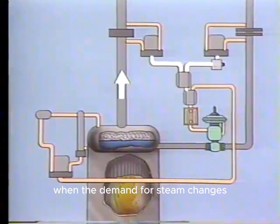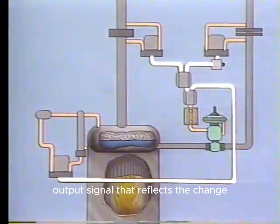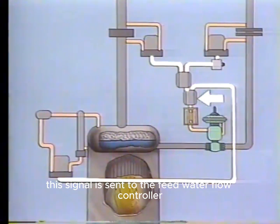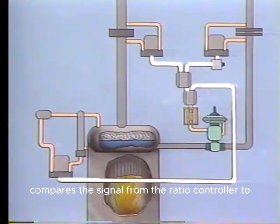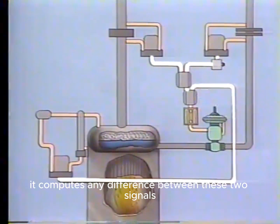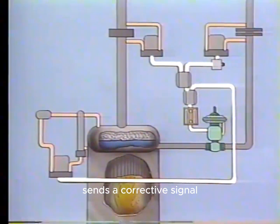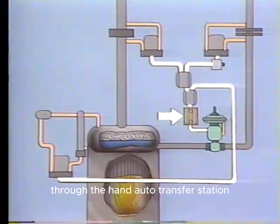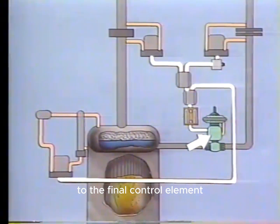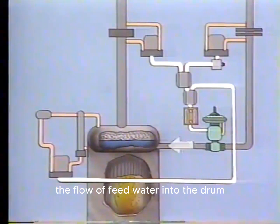When the demand for steam changes, drum level may also change, and the transmitter produces an output signal that reflects the change. This signal is sent to the feed water flow controller. The feed water flow controller compares the signal from the ratio controller to the signal from the drum level transmitter. It computes any difference between these two signals and compares that difference to set point. The feed water flow controller sends a corrective signal through the hand auto transfer station to the final control element. The final control element repositions the valve to change the flow of feed water into the drum.